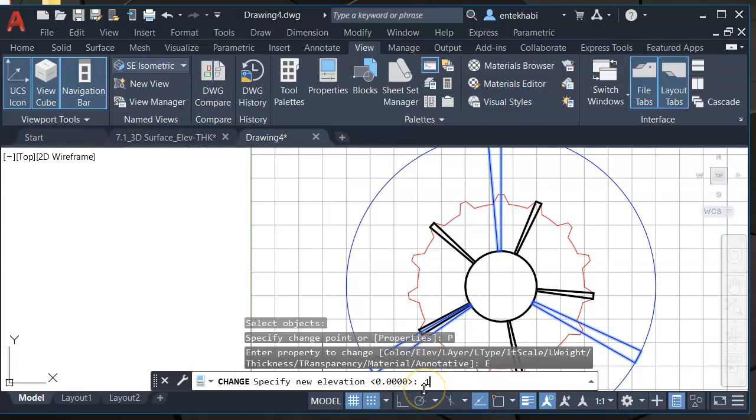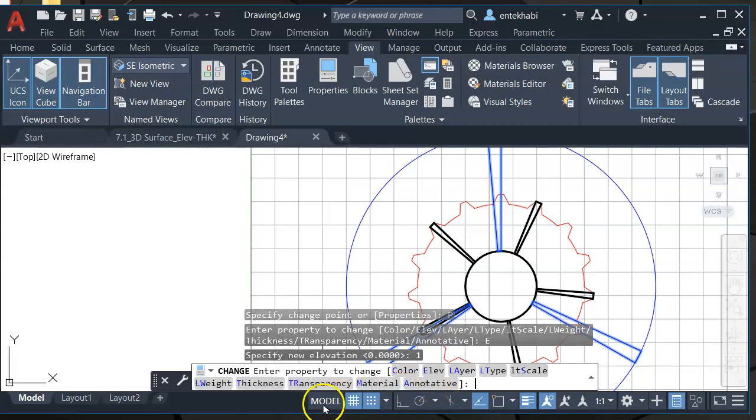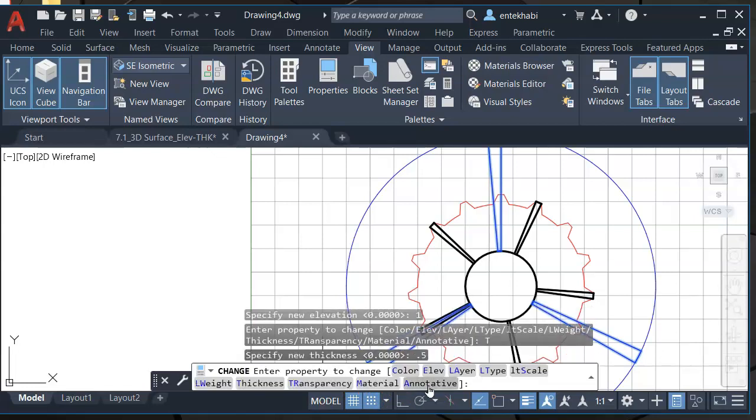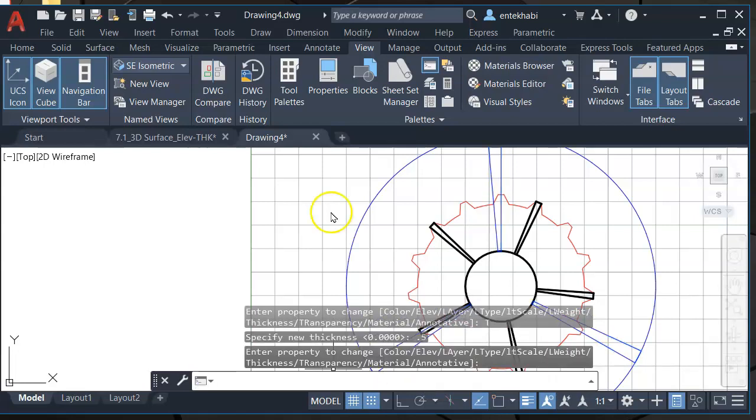And remember, default elevation is 0. If we don't change, everything is on the same plane of x parallel to the desk. That would be 0 elevation, and then everything goes higher. We change that for defining the z-axis this way. And again, this is one of the ways for creating the 3D surface model or solid model. We can define x, y, z values quickly.